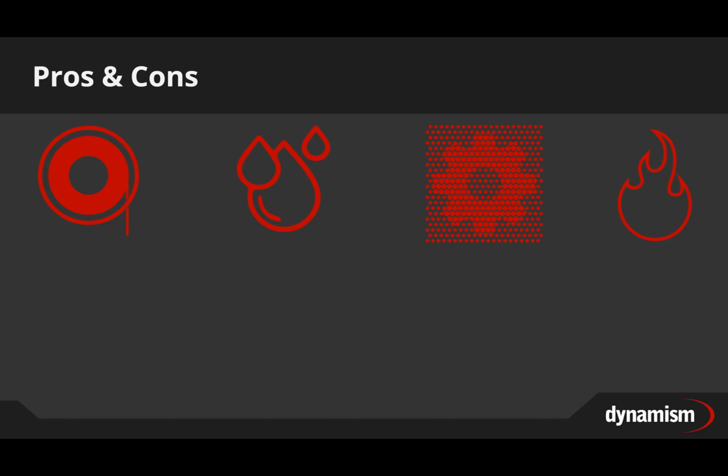On the cons, there's a trade-off between surface finish and the amount of time it takes to create your model. And your designs can be orthotropic, so you do have some weakness along layer lines. You will get strength in one direction, and in other directions you really fall short.